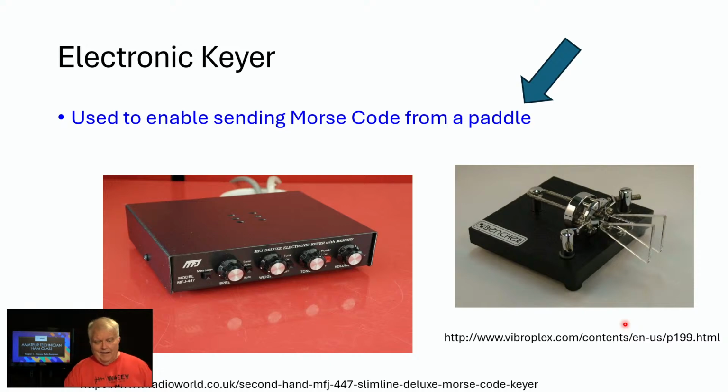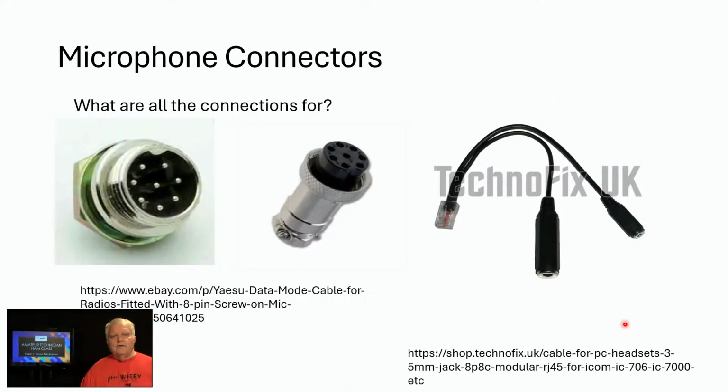Speaking of plugging in, microphones, the 8-pin Foster connection, which you're looking at there on the left, is a kind of standard connector that you see on various radios. The problem is there is no industry-wide standard. So the major manufacturers like Flex Radio, Yaesu, Kenwood, ICOM, they use the same connector, but they wire it differently. So just be aware of that.